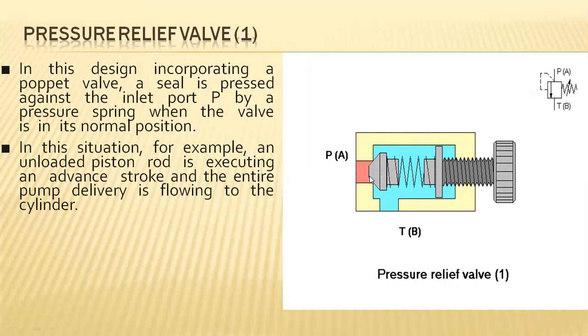So at that particular time, the inlet will be getting opened up when the set pressure is kept here by throttling. If 3 bar of pressure needs to be entered into the circuit system and towards the output to activate the actuator, the 3 bar of pressure will be set here, opposed by the spring, and hence that tension will be created in it.